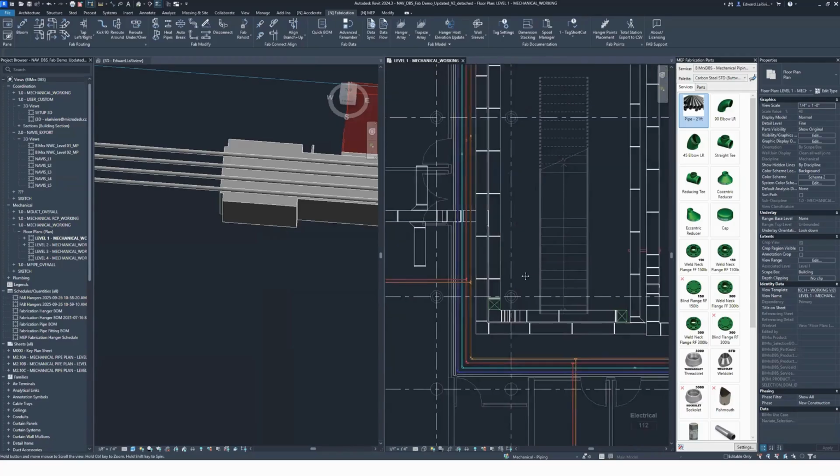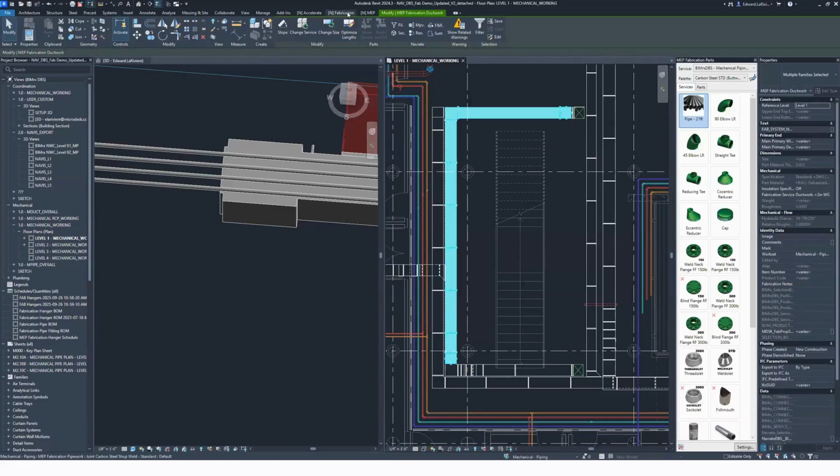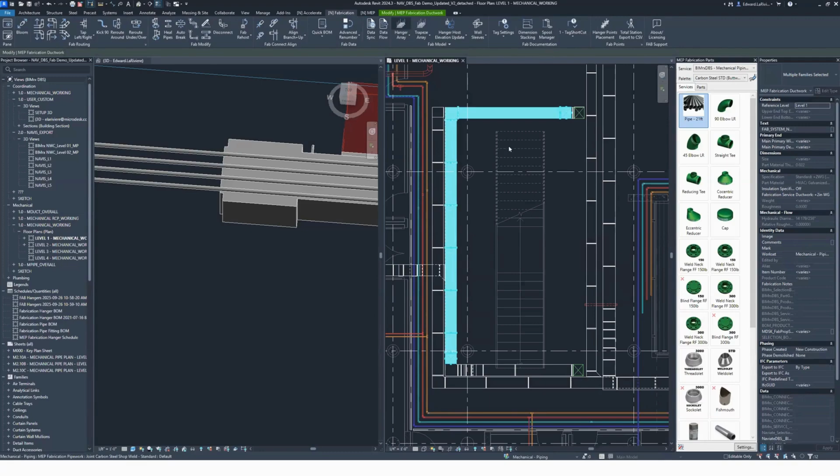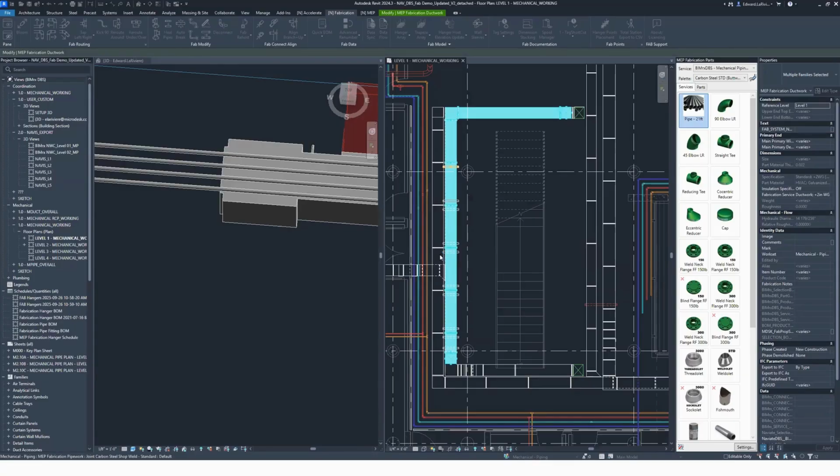Phenomenal. So moving over to this side, we've got a whole set of some pretty nice hanger tools waiting for us. Realistically, you just have to set those things up and then they're ready to run. So if you have someone else at your company that wants to set these things up for you, you just have to start grabbing elements, saying run my hangers, and we're going to see that thing run right through here, place a whole bunch of hangers for me, snap into structure like we'd expect on an ITM-based hanger, and following all these rules we've already set up.